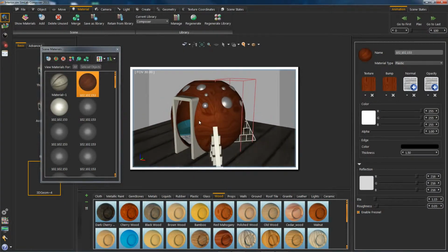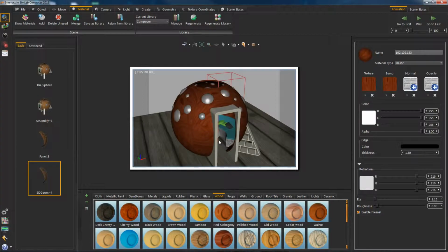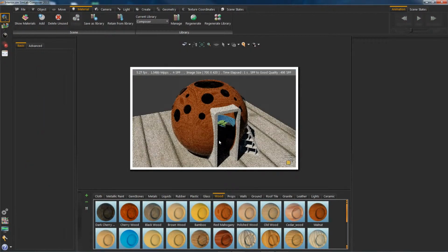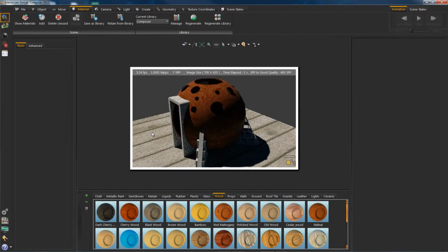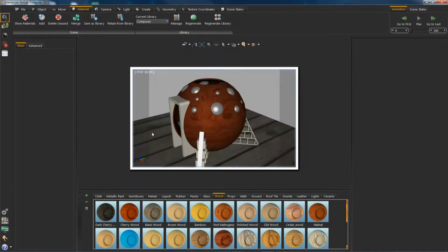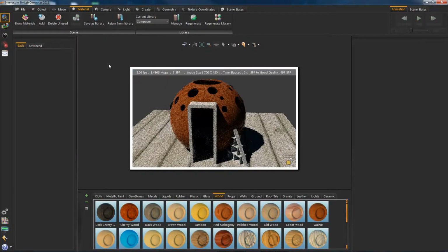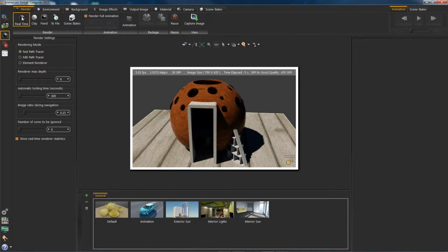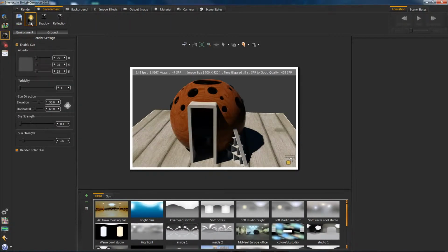So now to quickly do a preview render, just press F4 on the keyboard. Notice we have a sun lighting with this project. Let's go ahead and examine different lighting methods. Open the Rendering Workbench in the Environment Task tab. We will uncheck the sun light source and check the HDR instead.